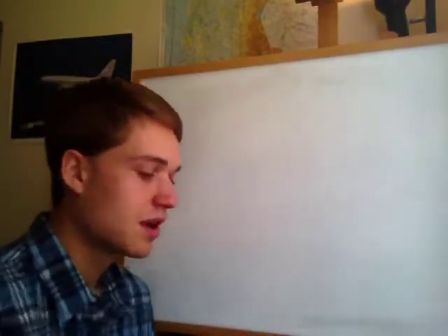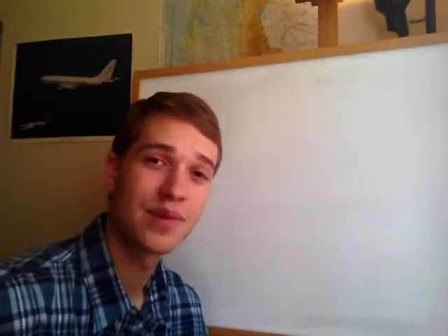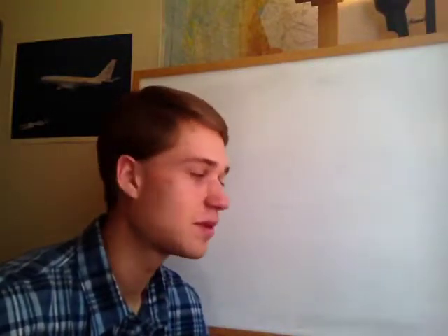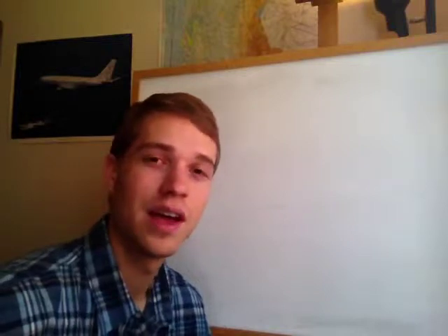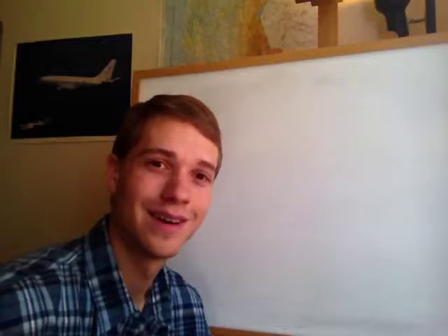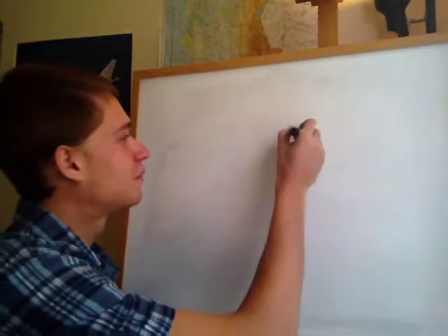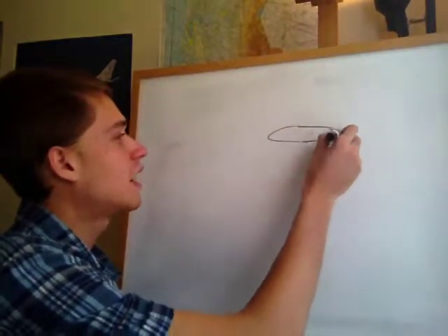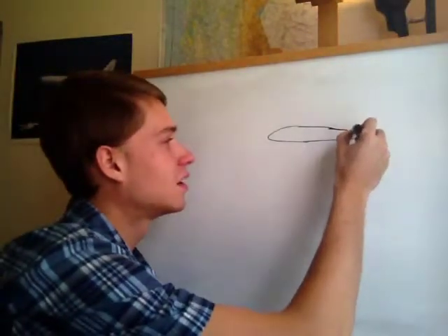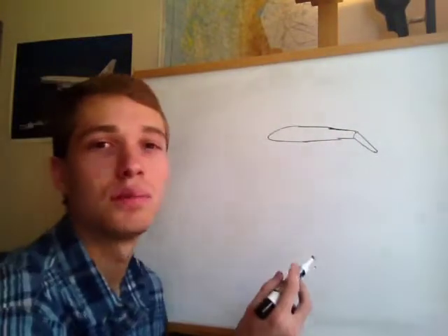Okay, so that's trim tabs. That's one of our secondary controls. The other one that we're going to talk about is flaps. We've all seen flaps when we've ridden on a commercial airline. You look out the window at the wing, and during approach to landing, it's like the whole wing starts unfolding, and it's quite an impressive sight. That's because they're lowering the flaps. Very simply put, a flap is almost like a one-way aileron. You deflect it downwards. And this one right here that I'm drawing is just called a plain flap.